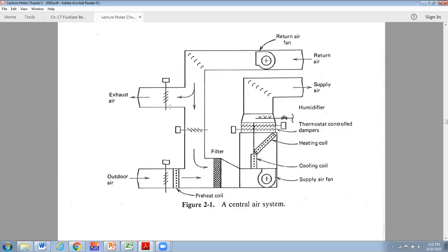We show here, we have an exhaust damper, or if we're talking in terms of an economizer cycle, this could be called a relief damper to relieve pressure in the space. Either way, it allows some of this return air to be vented to the outside under the control of this damper. So if this damper is wide open, then this damper would be shut or mostly shut, meaning we want to expel this air, and we're probably in economizer mode. If we're not in economizer mode, we would probably not want to expel too much air, maybe a little bit for pressurization on the space.